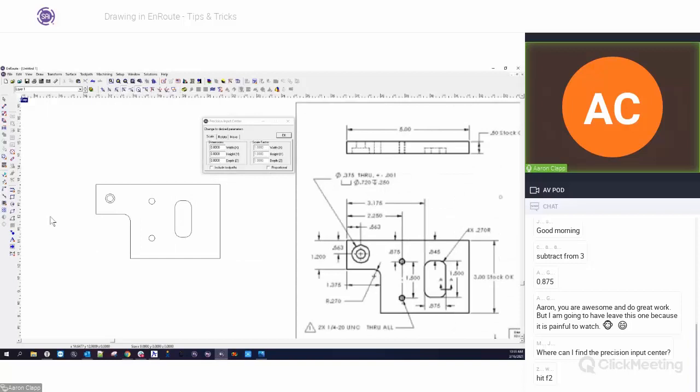Now I can toolpath this. So I just grabbed another line, made it 1.5 inches, snapped it to the center, and then made a copy of my hole, and then dragged it down to the end, snapped it into position, and put it in like that. So this is one way to draw. Now there are, like I said, many multiple ways of doing this. You'll find that you can do it this way, you can do it another way. There's all kinds of different ways to do it.